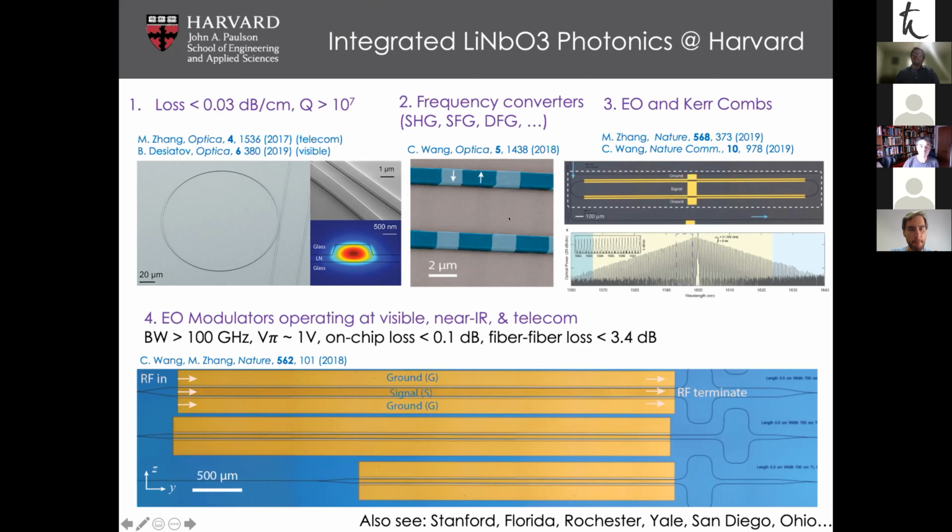We demonstrated with Marty Fejer also a periodically poled thin film lithium niobate platform that allows you to actually do frequency conversion to go from, let's say, a red photon to a telecom photon. We have very nice, very fast modulators, with bandwidth in the hundreds of gigahertz that can operate at very low voltage, very important for photon shaping. And we can also realize various types of frequency combs that could be interesting for some sort of frequency domain quantum computing. I'm going to briefly mention that.